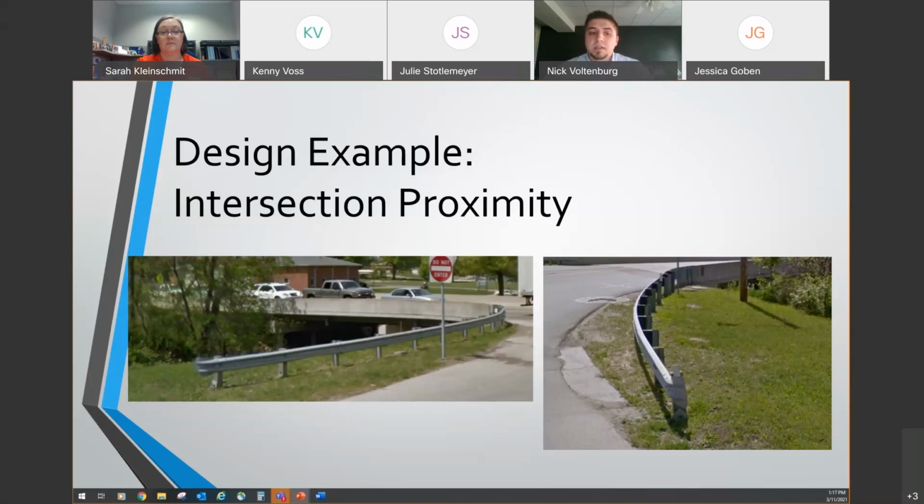However, to highlight what we touched on before, this becomes a situation where it may be a while before that guardrail is touched again, unless damaged. And like I said earlier, we do not want to kick the can if we are in a position that we can upgrade it now. If you look at this guardrail, it's very old and it is shorter than the minimum 27 3/4 inch height that we at least recommend for our guardrail to meet.